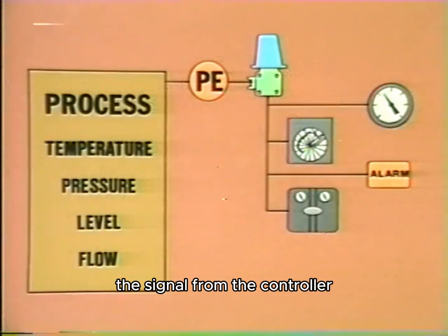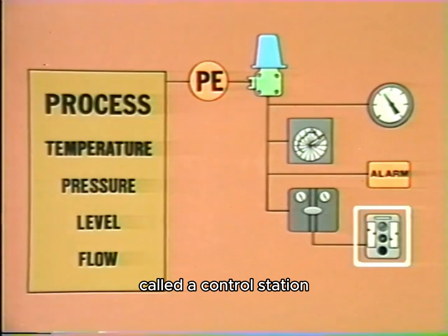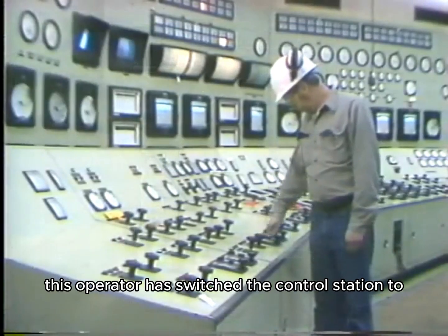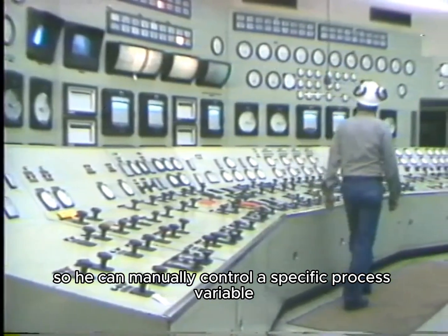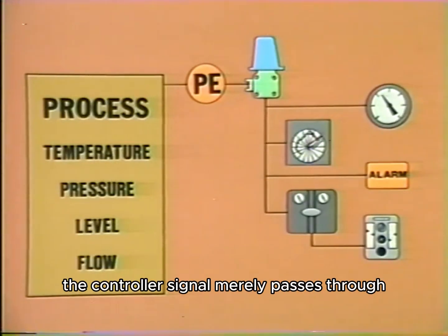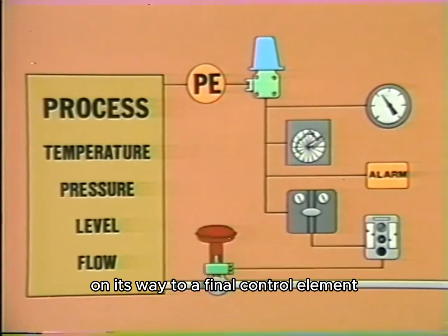The signal from the controller is frequently sent to another type of instrument called a control station. A control station allows an operator to control a plant condition manually if necessary. For example, this operator has switched a control station to manual so he can manually control a specific process variable.